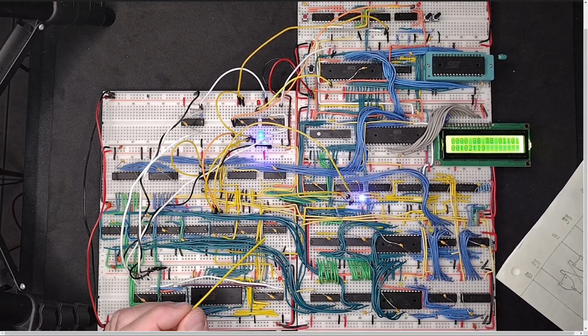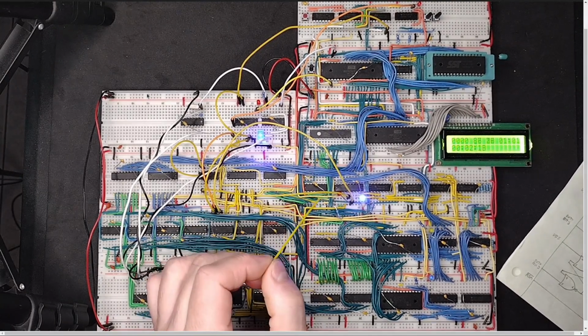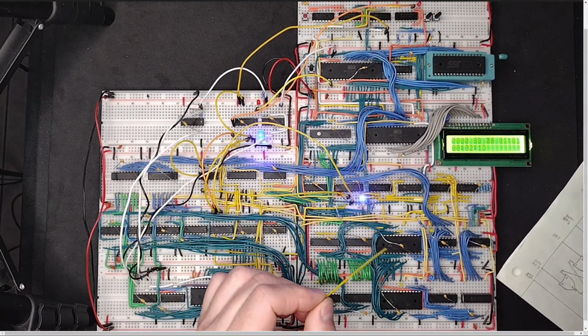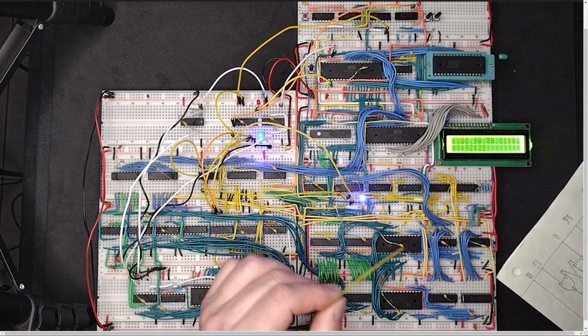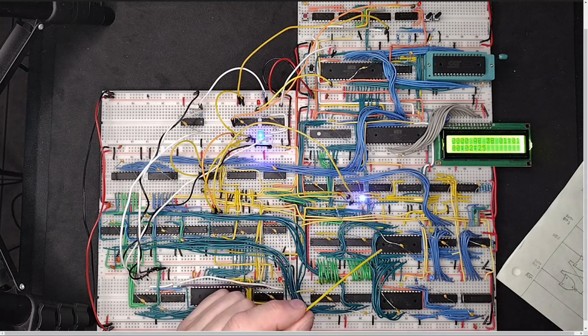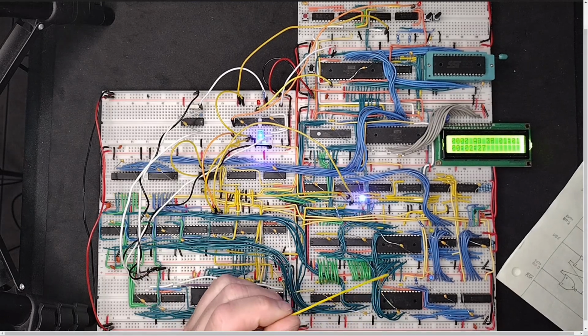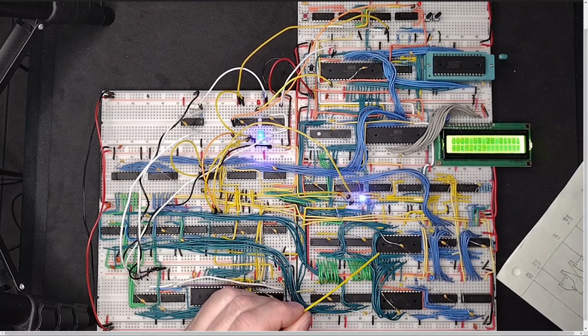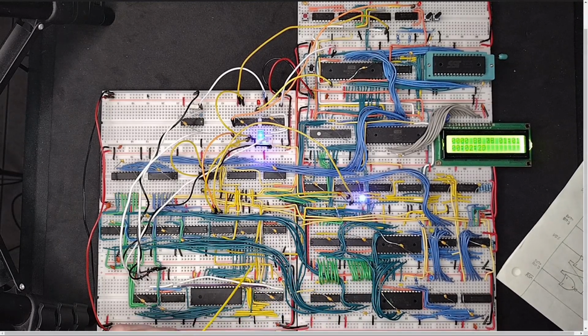By the time I were to, for example, set up my memory, change the clock speed to 5 megahertz, and talk to the background RAM or the foreground RAM, and after that's all done, I'm out of clock cycles. I can't actually do anything useful. So I'm going to do all my useful stuff on the video card during the vertical blank interval.